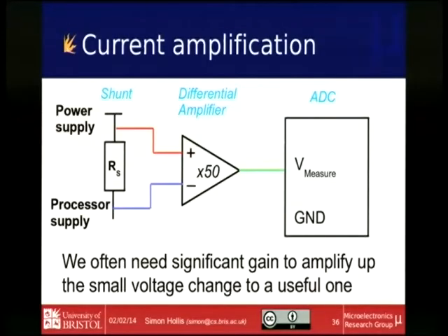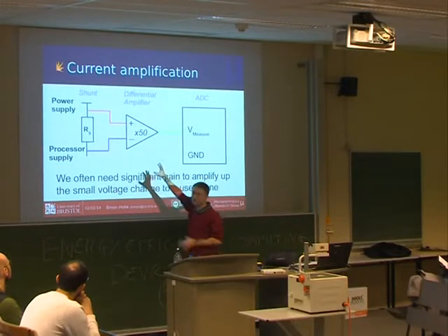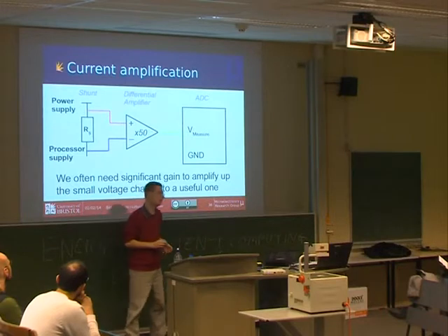So what we do is amplify the voltages that we see in the analog domain. We don't just create that differential voltage, we also amplify it at the same time. We amplify by a factor of 50, and that scales 0.05 volts up to 2.5 volts. So we can cover the exact range that the ADC is fully sensitive to, and that makes it much more useful. So your question then is, how do you build that differential amplifier?